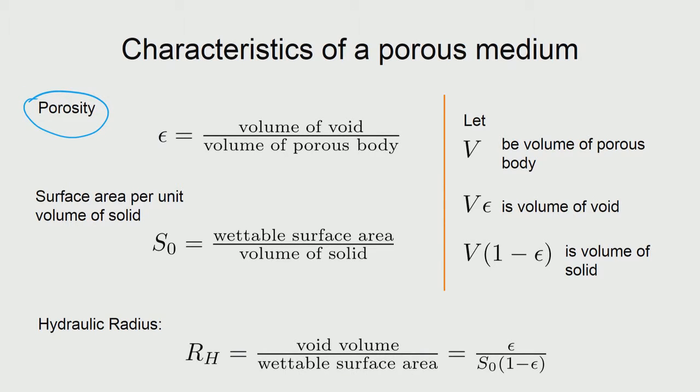If you take, for example, a powder bed and you are using powder metallurgy principles to sinter it to a solid block, then depending upon the extent to which sintering is happening, you would have porosity changing. So as the density approaches the theoretical density, the porosity is approaching 0. If you stop in between, you can achieve a porosity between 0 and 100, like 50% porosity, 70% porosity, etc.